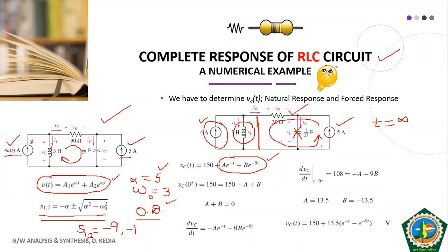So the voltage that we will come across this VR will be, current is 5 ampere, resistance is 30 ohm, that is 150 volt. In fact, if you look at the sign convention that we have used here, then VR will be -150 volt.